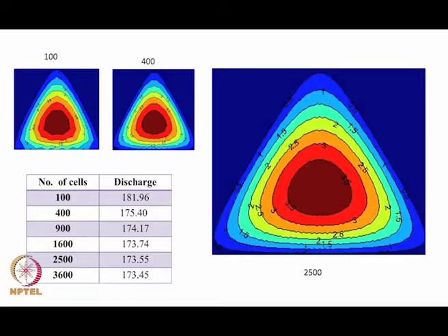So, this is essentially what CFD is, but this is not the only aspect of CFD, because what we have done is take the simplest possible case. In an actual case we have a lot more difficulties that we encounter. The equations that we have taken are only a Laplace type or Poisson type of equation. So, in that sense it is probably the simplest form of the governing equations that we can find in fluid